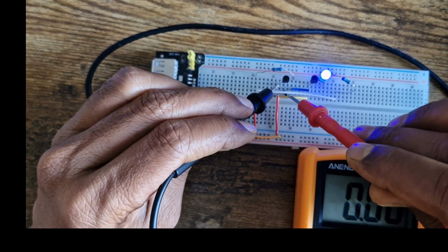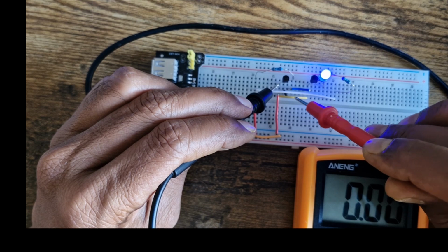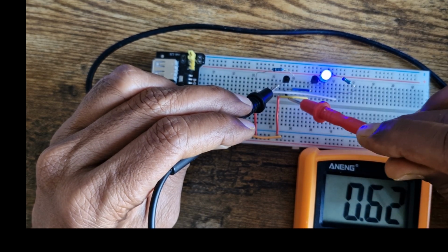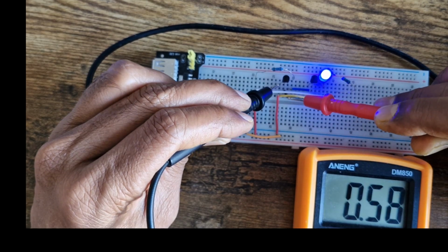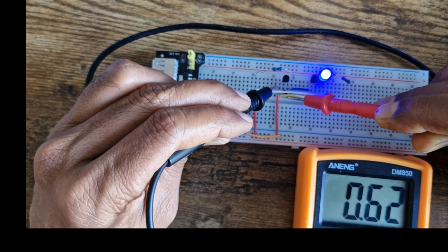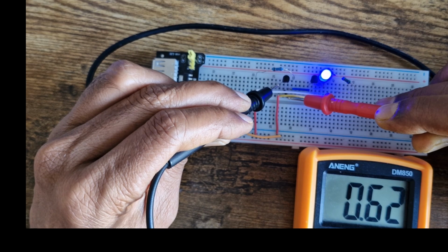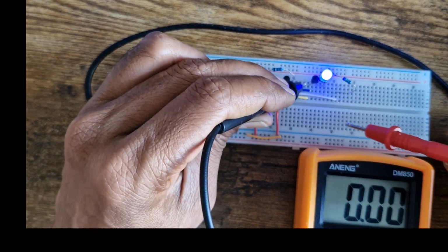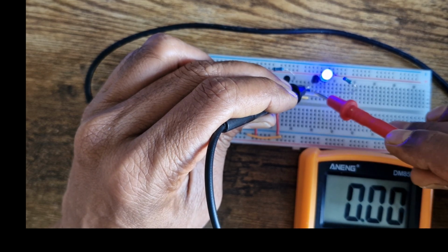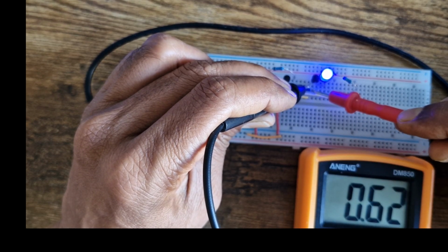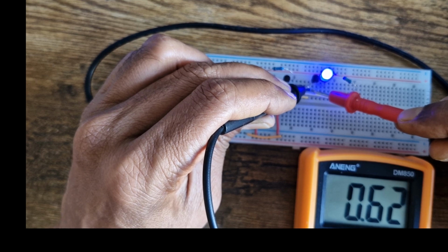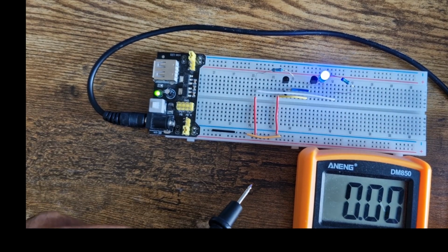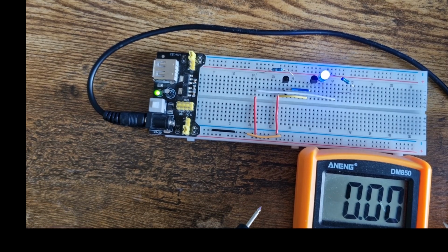But here I make a possibility of shorting the lead, so I have to make sure that I am accurate in doing that. So here is the base connection possibly, and you see that this is the forward voltage drop of around 620 millivolt of this transistor. And similarly here also you can make this around 620. So these are exactly identical. Okay, so this is how you can actually measure it, right?